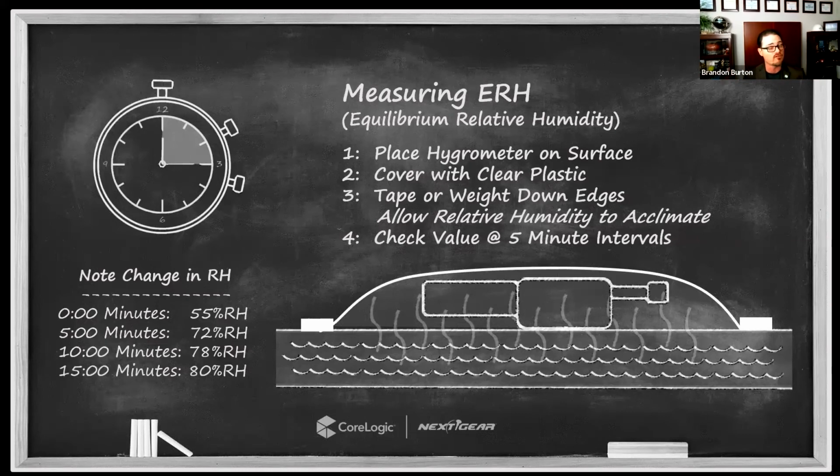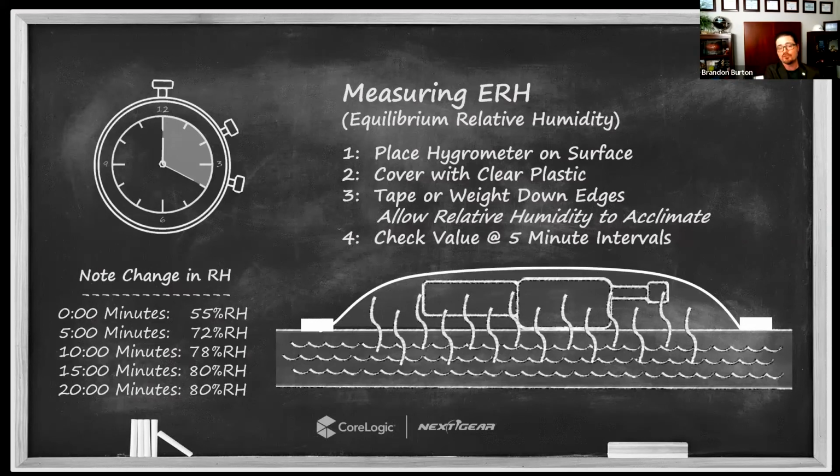The relative humidities are only changing by a couple of percentage points. At that point, it's close enough that you could probably begin your analysis. But if you want to be really, really particular, come back in another 5 minutes and verify that the 80% hasn't changed, right?